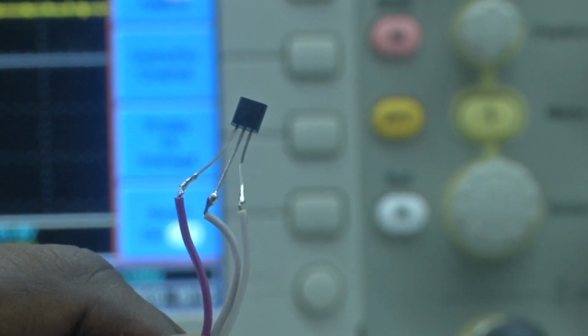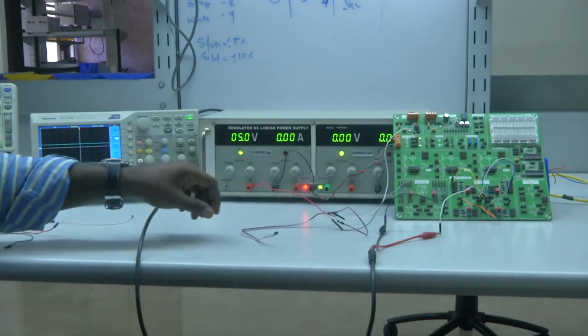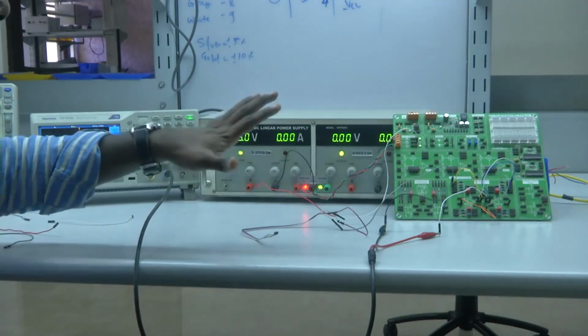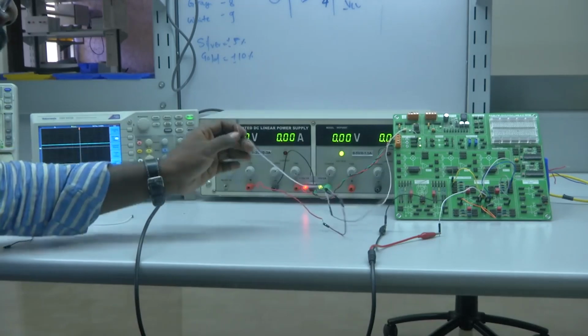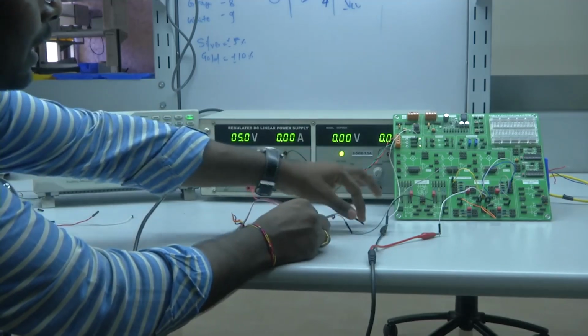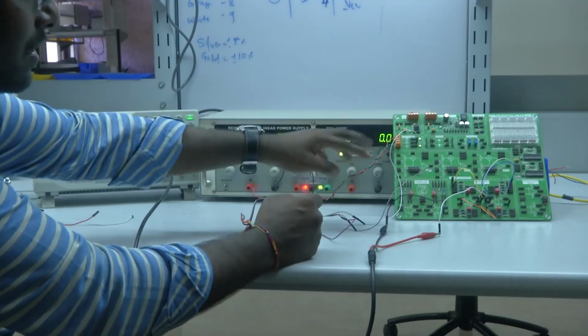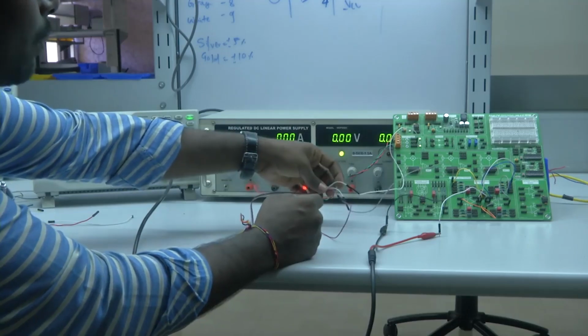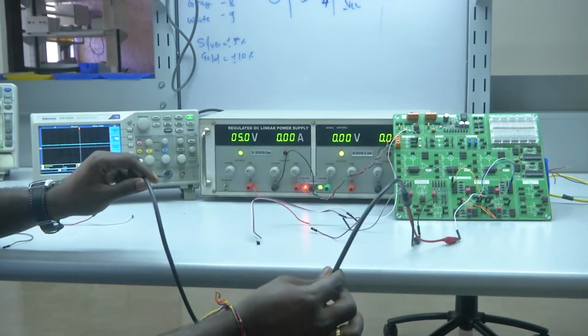Let me connect it, then we will use a heating station and observe whether we are getting any changes, or whether we are able to measure the temperature of the heating station. Now if you see the connections, we have replaced the input side of the operational amplifier with the LM35 temperature sensor. The LM35's input is connected to 5 volts, the output is connected to the resistance of the first stage of the inverting amplifier, and the ground terminal is connected to ground. The output can be measured using this particular CRO probe.